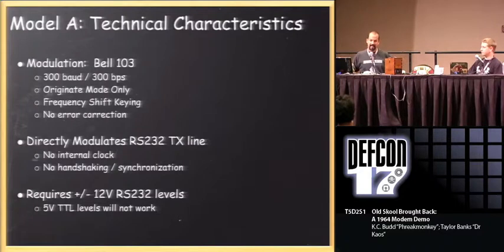The reason they did that is because in the 1950s, when this was proposed as a standard, its purpose was to be able to put peripherals like terminals to mainframes around, say, a big campus or office environment. This was the only networking we did at the time other than like thick twinax on 5250s and what have you. So that discrepancy is to deal with the resistance of just straight copper wire over several thousand feet. So you could put a terminal 2 buildings away from a mainframe and it would still work.